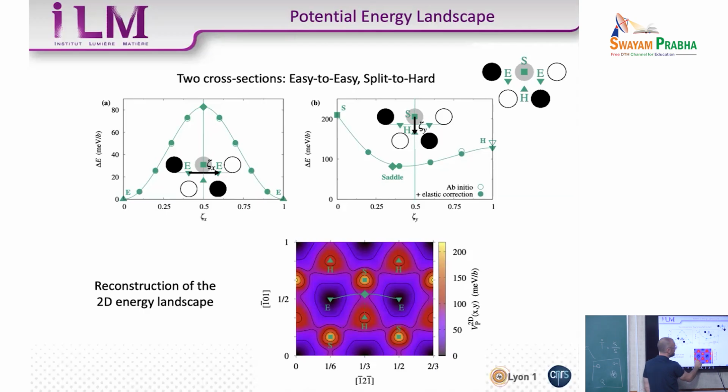But what we have seen by looking at where the core of the dislocation goes along the NEB path is that there's only one case where the path is really linear, it's iron. In all other systems, the path will be deviated towards the split core, always.